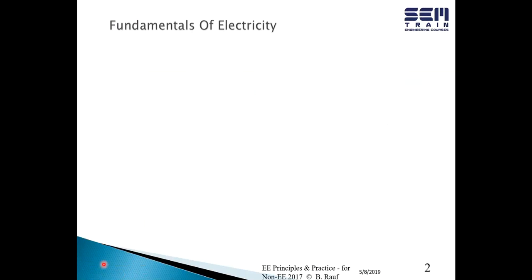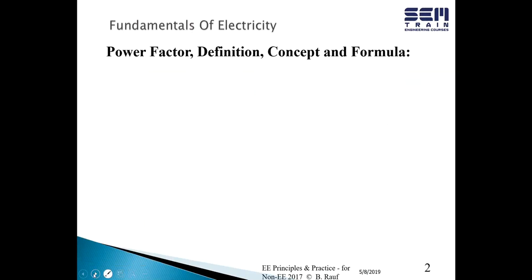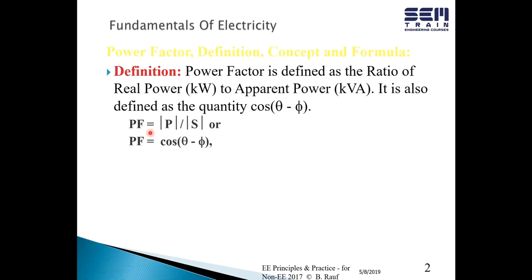All right. So you've already heard me mention the term power factor a few times. I think I've mentioned in one of the foregoing segments that power factor can be defined two ways. It can be defined as a ratio of real power divided by apparent power, or it can be defined mathematically as the cosine of the angular difference between the voltage angle and the current angle. Cosine of that. So we can calculate the power factor either way.